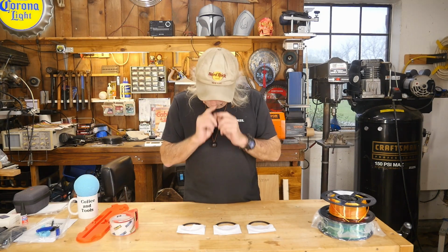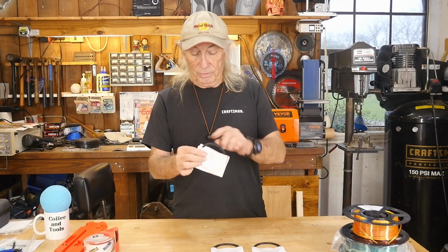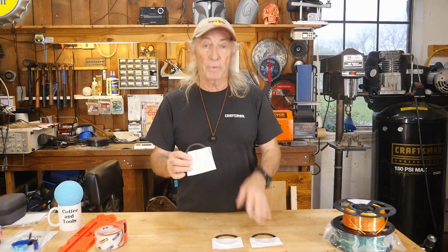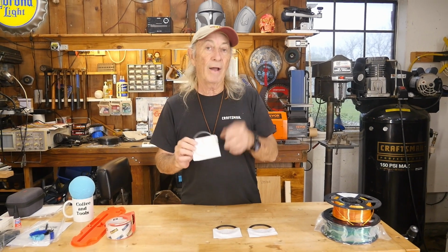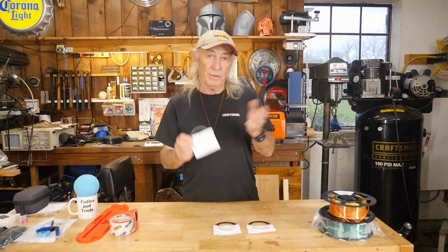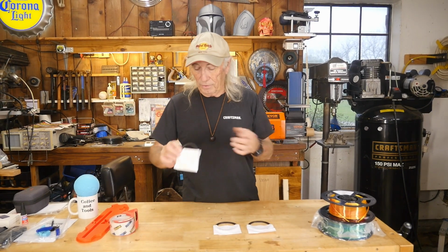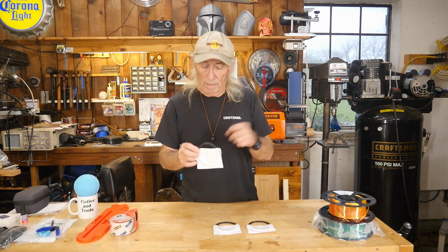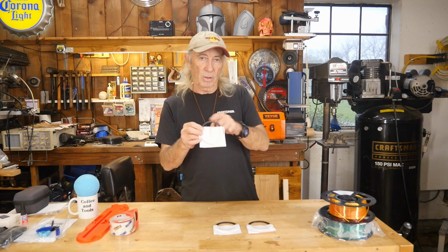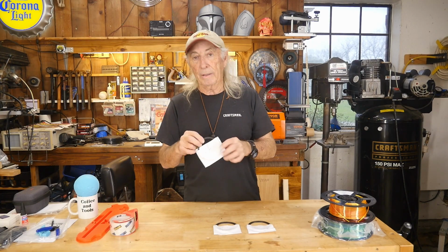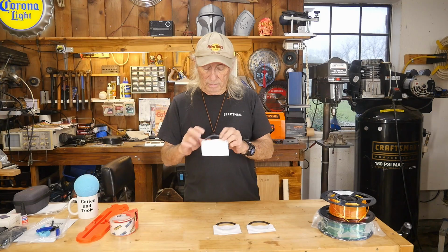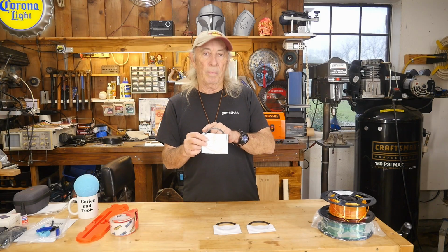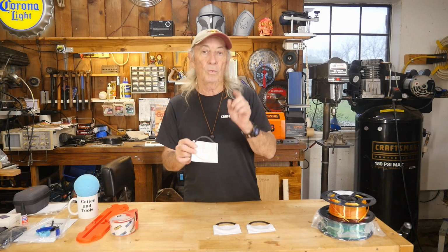We were having a problem with the roundness right here. These are samples of different file formats that I sent over to the printer to see if there was any difference once we fixed the problem. It's getting this flat spotting going on here, which apparently, and I'll take you to the screen and show it to you, I had to change my density setting to 1.0.